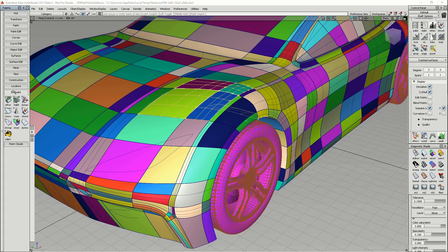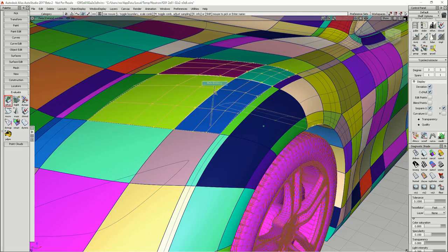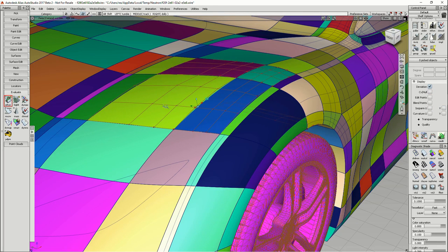What's also cool about these is that if I go in and start checking the continuity, what did I do wrong? For those that aren't familiar with Alias, if you see the C on the screen, that means it's checking for curvature continuity. And if it is not green, that means it's not behaving the way it's expected to be. And here we've got a green bulb saying that we actually have curvature continuity between each one of these patches. So are these dumb surfaces? You know, maybe, but they're curvature continuous. They're real surfaces, and you can use these to combine surfaces and start to work from it.